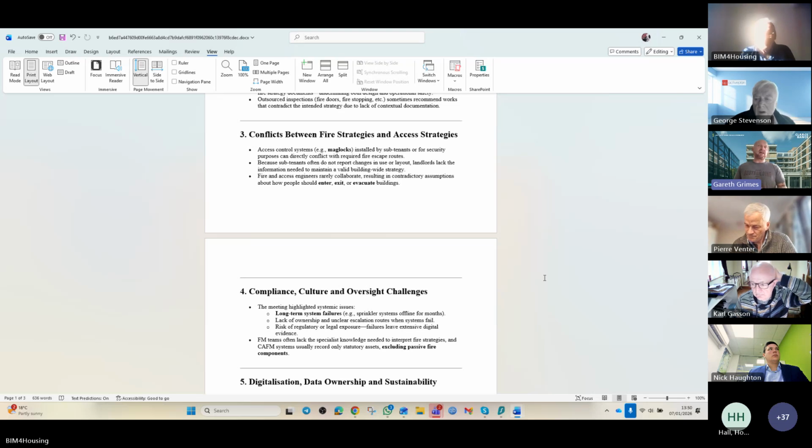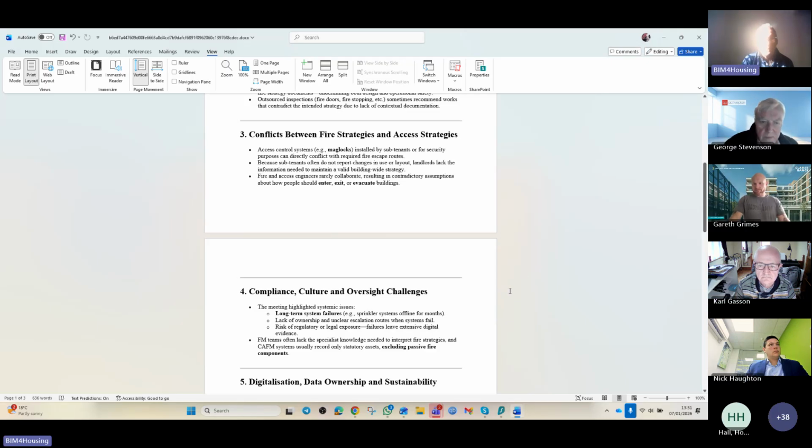And what I'm advising clients is to generate an asset management plan that covers off any of your maintenance, whether it's dampers, fire doors, etc., and giving them a clear pathway process of what it triggers in other parts of regulations that need to be updated. Reg 38 pack, fire strategy, fire risk assessment, whatever it may be, because people are just basically taking an asset and going, right, I need to put bums in beds, but they don't understand that any decision can have a knock-on effect to the end user. So I agree. Okay, right, let's move on.